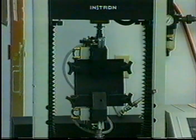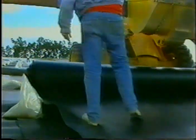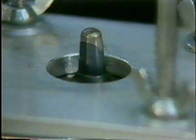Tensile strength can be measured in a uniaxial test or a biaxial test. Survivability refers to the geomembrane's ability to survive construction. Survivability is evaluated by a series of standard tests for puncture, burst, impact, and tear.